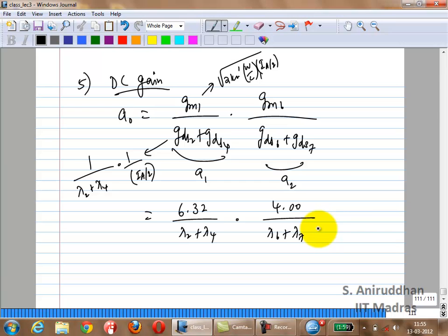You need to design the length for a particular lambda which will give you this particular gain. Now last time when we did the folded cascode, the telescopic, we actually did it a different way. We put in values, found out RDS and put in assumed L-min and so on. And we actually got RDS of the P very different from RDS of the N. We'll go the opposite way here.